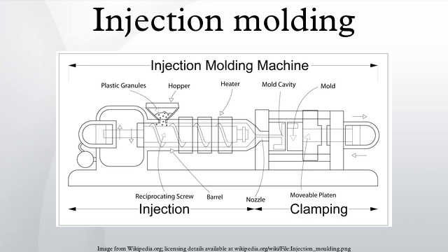Injection molding is widely used for manufacturing a variety of parts, from the smallest components to entire body panels of cars. Parts to be injection molded must be very carefully designed to facilitate the molding process. The material used for the part, the desired shape and features of the part, the material of the mold, and the properties of the molding machine must all be taken into account. The versatility of injection molding is facilitated by this breadth of design considerations and possibilities.